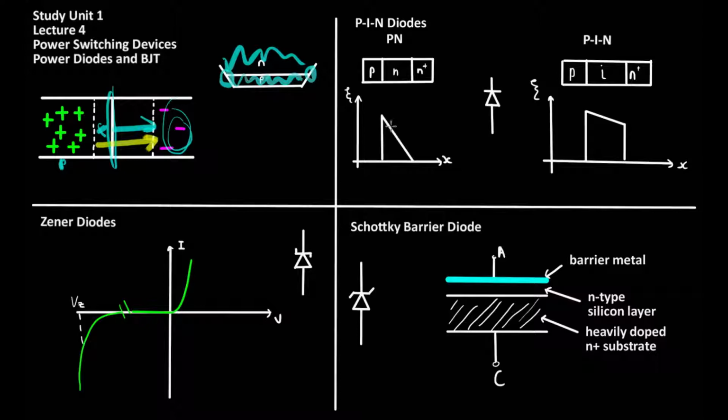One of the problems with making diodes out of thicker and thicker wafers of silicon is that the transient properties of the diode start to degrade. In other words, the thicker the junction area, the worse the ability of the diode to switch from one state to another. The problem of very thick wafers is overcome by using a new diode structure. These structures are called PIN diodes, where the I stands for an intrinsic doping profile which exists between the p and n regions of the diode, in a way to customize the intrinsic region in the diode over here.